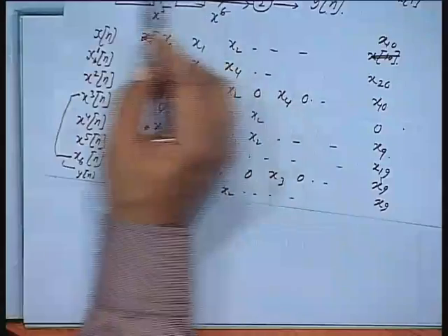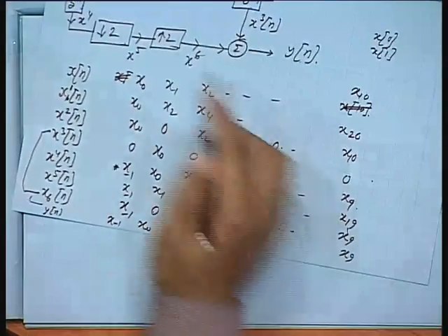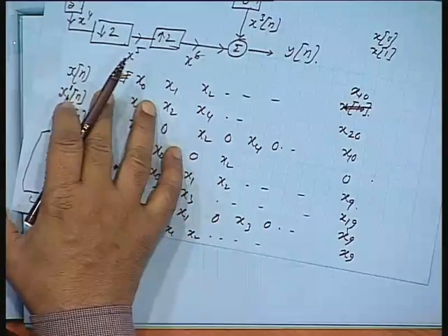So, they are complementary to each other. Individually, you see there is an upsampler and downsampler by the same factors. There is a delay element, there is a delay element here also, but they do not produce the same sequence. x6 and x3, they are not same. Though I have taken the downsampler and upsampler in the same order, I have just changed the positions of these two delay elements and they generate two different sets. That means this entire operation is not linear. It is linear, it is not time invariant. In the time domain, they are not invariant.